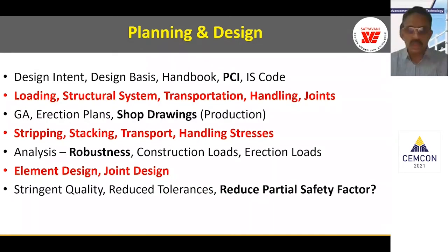Construction loads and erection loads are to be considered, and element design and joint design are to be very clearly taken care of, with stringent quality, reduced tolerances, and reduced partial safety factors which can come in future codes. As you're all aware, we use the same partial safety factor whether we are doing precast, using the best construction company, or using very bad contractors or very bad construction practices.